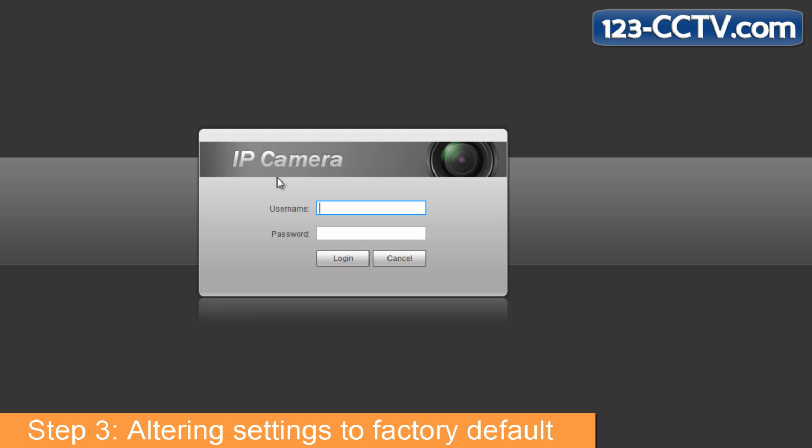If you are using a PoE NVR, you may return the computer's NIC settings to their original state, disconnect the camera, and attach it to the NVR. If you are not using a PoE NVR, you can configure the camera to the settings that you need and attach it to the network again.